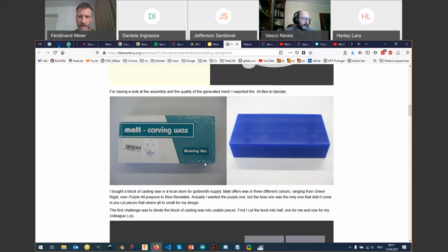If you take aluminum foil and put it into a wooden box, then when it contracts, it will wrinkle the aluminum foil, so you get a very coarse surface. In any case, you have to cool it down very slowly. So you should just leave it in the oven and let it cool down over an hour or two. So you get a smooth block. It will shrink, so it will retract from the edges. That's the good thing.